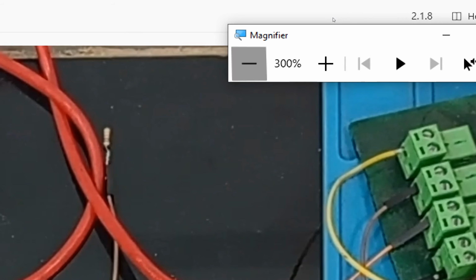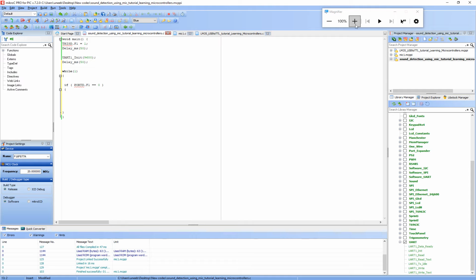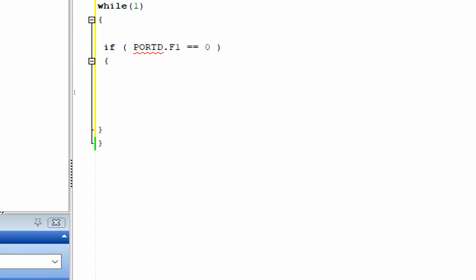So we give a delay here, that if the sound is still there for more than some time, only then consider it a whistle. In this way we can make it a whistle detector. So similarly, you can play with this delay to detect various sounds. Like if the same pitch is there for a long time, it means it's that sound. That's how you play with this.